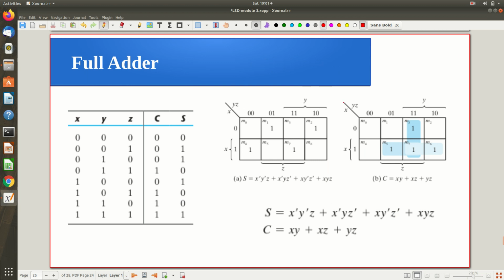So now we need the generalized adder, where you should be able to consider the bits as well as the carry that is coming from the previous bit addition, right? So it is something like this. When I add two bits, ith bit of the number A and ith bit of the number B. So two numbers I am having, A. So let me take this is my first number, some n bit number, A0, 1, 2, 3, some n minus 1. So like the total n bits are there. So B is another number containing n bits, right? B0. So 2 n bits number I am having.